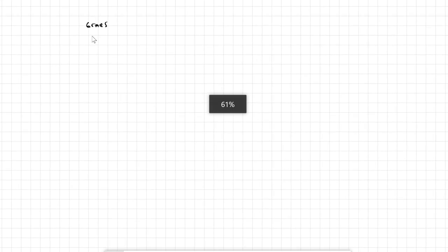Alright, so a quick summary about gears. We saw three relationships. The first one was that the circular pitch of two adjacent gears should be the same so that they match. If the circular pitch, which is just the distance from here to here, is not the same as the next gear, there would be interference and it would basically not work.